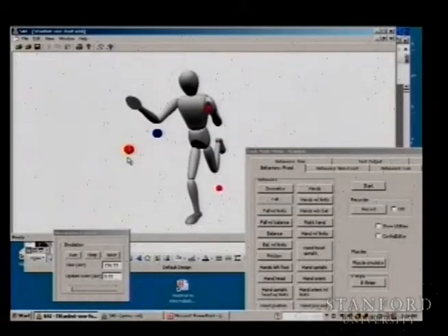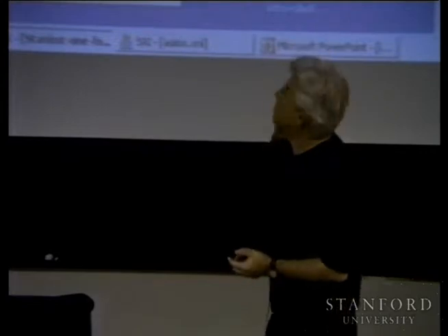So let's say I would like to move this to here. How can we do that? The hand, I would like to move it to this location. Forward or inverse kinematics? Oh, very good. Well, the forward kinematics gives you the location of the hand. The inverse kinematics gives you, given a position for the hand that you desire, the joint angles you have to have. And if you do that, then you know your goal position angle for each of the joints. Then you can control these joints to move to the appropriate joint positions, and the arm will move to that configuration. Well, can you do inverse kinematics for this robot?